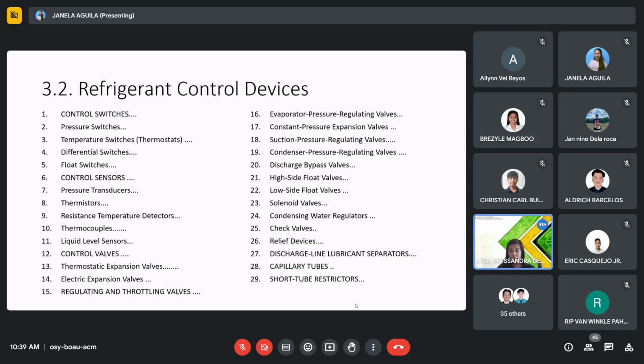It's due to their capacity to control the refrigerant flow from the high pressure side to the low pressure side. And also they facilitate phase change and optimize evaporator efficiency. Thus, these tubes can be classified as restrictive devices, which employ a flow restriction to further regulate the amount of refrigerant entering the evaporator.